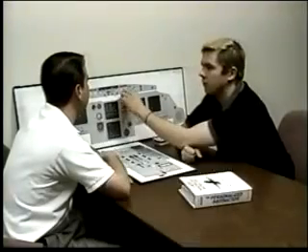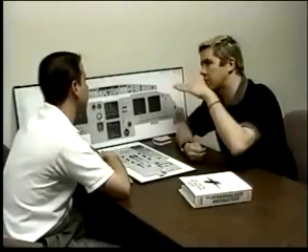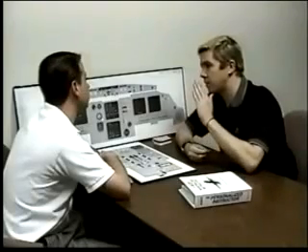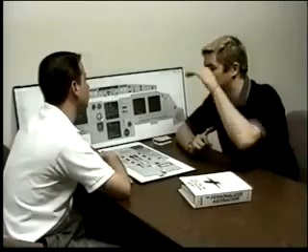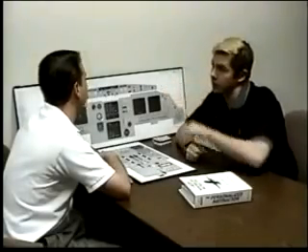If I push it, it's asking for a vertical speed of 0. That doesn't mean the airplane's going to level off at the altitude I pushed it at. It means it's going to decrease its vertical speed to 0. So if I push it, and I'm doing 2,000 feet a minute in a climb, as I pass 3,000 feet and I push it, it's not going to come back down to 3,000 feet. It's just going to level off wherever it achieves 0 VSI.